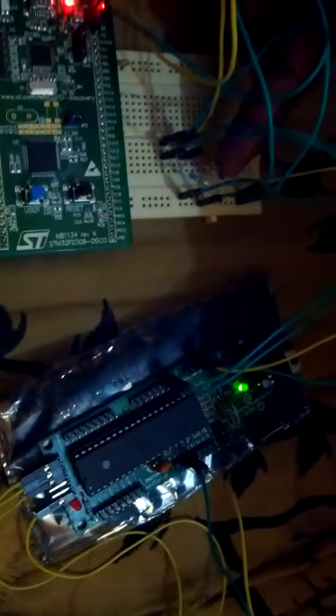the I2C specs or two-wire interface specs. That means both SCL and SDA lines have to be connected to the 5 volt supply with the help of 10K. I have used a 10K resistor over here, and most of the time a 10K resistor will work, but when it comes to devices it is safe to calculate the resistance that we have to connect between the SDA and SCL lines.